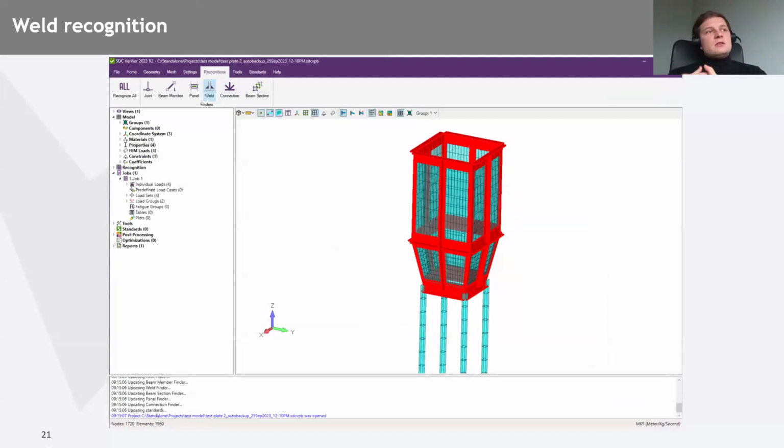And then the stresses in these welds, in this case, are reoriented into the weld direction. The forces in these elements, if it's a beam member check, for example, are summarized to be taken into account, or force balance in the joint is taken into account for further calculations.